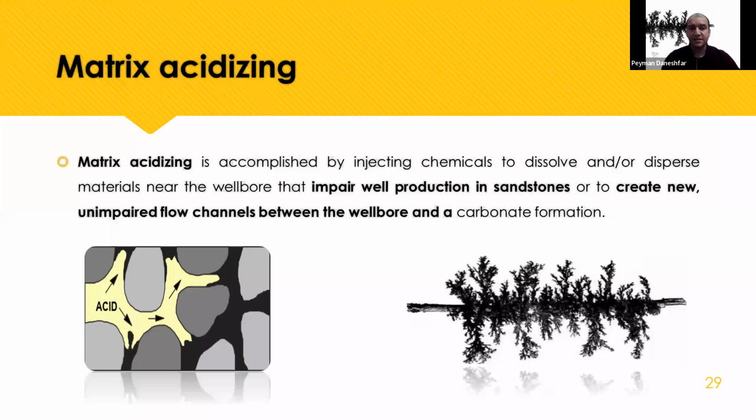So acidizing in a carbonate formation is much more important than in a sandstone formation. Sandstone formations are important, but in carbonate formations, if we do acidizing jobs, we improve the production. In a sandstone formation, we just come back to our previous production.